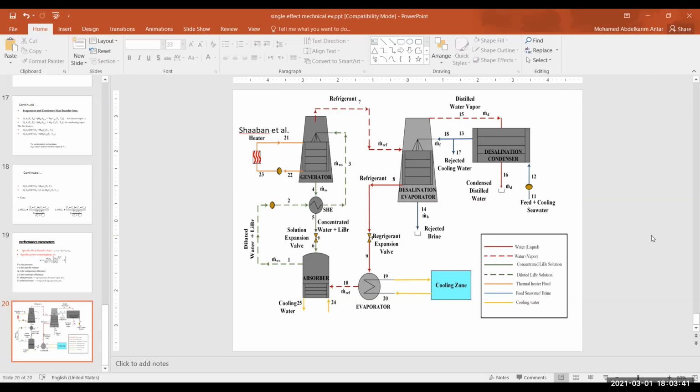Not only silica gel, but lately there has been a family of MOFs, which are metal organic frameworks, that are being used for generating cooling effect through adsorption. And we have done some work even for doing adsorption and connecting it into a desalination system. We have a student that defended his master last semester, and he was doing a combination between adsorption and MED system. And there is another famous system that has been built in KAUST, where Dr. Ng and Shahzad Wakil have got a grant. They built a system they call MEDAD.